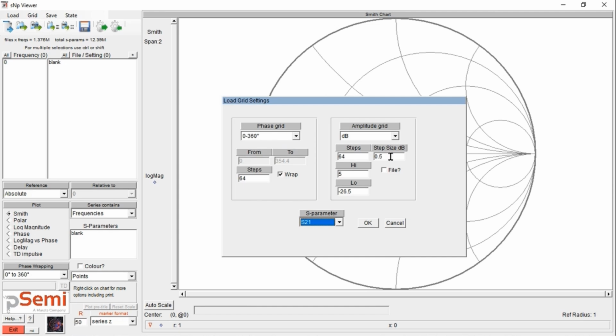It's going to be a 1/4 dB step size, and I already know that we want to take it from magnitude -10 to -25.75 in 64 steps. It's worth noting at this point that you can disable either phase and just do amplitude, or you can disable amplitude and just do phase. But in this case, we have a phase and amplitude controller, so we want to do both. We'll start the process.